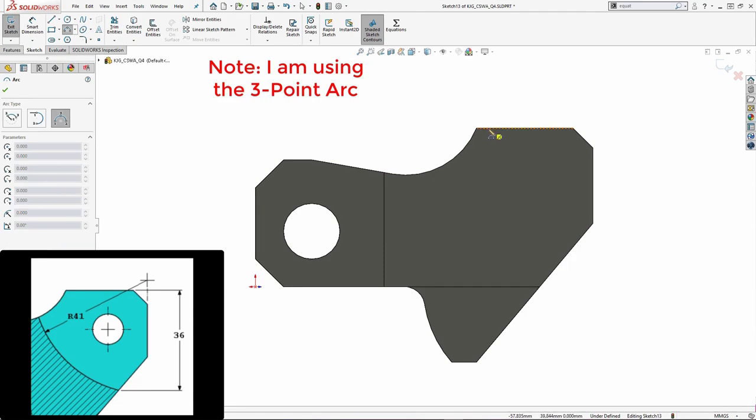And I'm going to start with my corner rectangle tool, and I want to make sure that I'm going to start coincident to the top edge and then end coincident to the side edge. Now don't accidentally constrain this to the midpoint. That will cause issues for you that you will then have to troubleshoot and go back and try to fix and change. So it's not actually going to the midpoint.